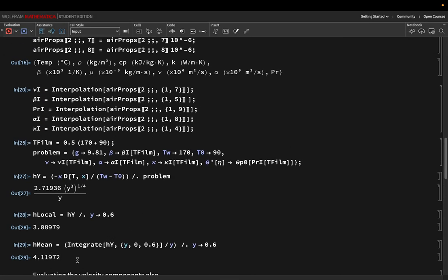Calculating heat transfer coefficient is clear, right? Are there any questions? Yeah, you can always take the correlations that are already there in the literature instead of actually solving the differential equation. You can take the correlation given in terms of Rayleigh number or Prandtl number, compute the Rayleigh number, and use the Nusselt number.